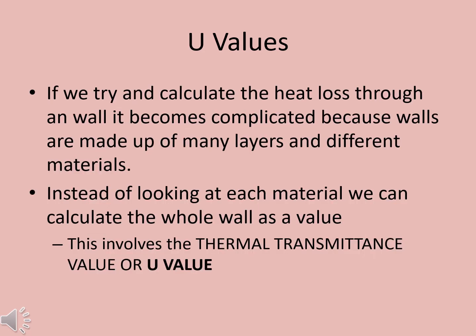Calculating heat loss in a building is a little difficult as the building structure and fabric is not made of just one material, but multiple layers of materials at different thicknesses. So instead of looking at each material separately, we can calculate the building element, such as a wall, as a single value. This will result in a total heat loss value known as the thermal transmittance value or U-value.